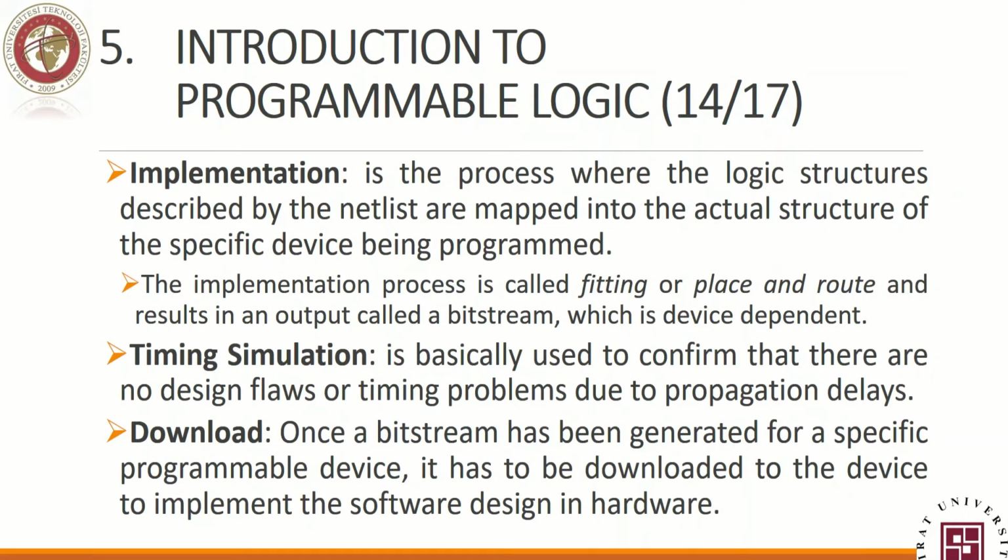Okay? Once we synthesize it, we need to implement it. Implement it, that means transferring it to something that fits exactly the device we have. So it's like mapping or fitting. Once we map it to our device, what we need to do is a timing simulation. This is the last part of testing.